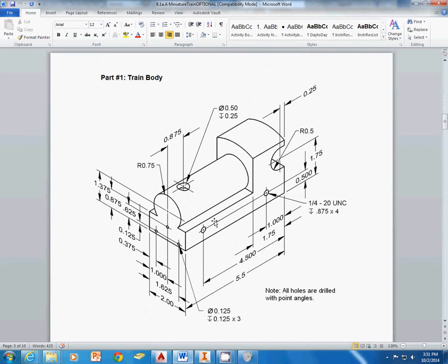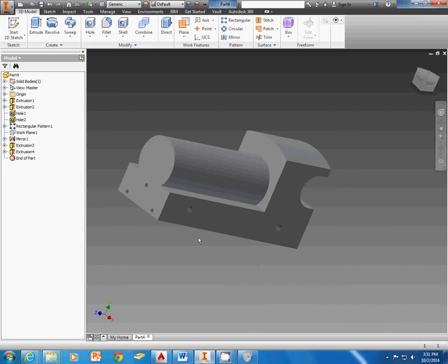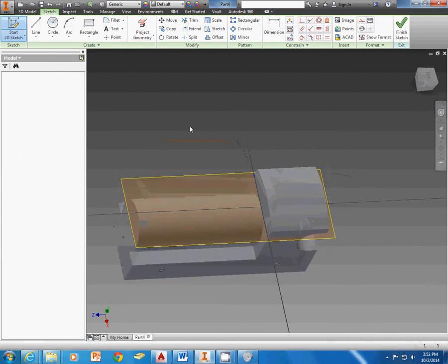To create the stack hole, we need to go ahead and use a plane again, is the best way that I've found. There, once again, is more than one way to do everything that we do in Inventor. But to create this, I'm going to click plane, pick the top surface there, and pick a plane parallel to the plane that I want. So once I've done that, I've got a plane setting up on top of that cylinder. I can pick the edge of that plane.